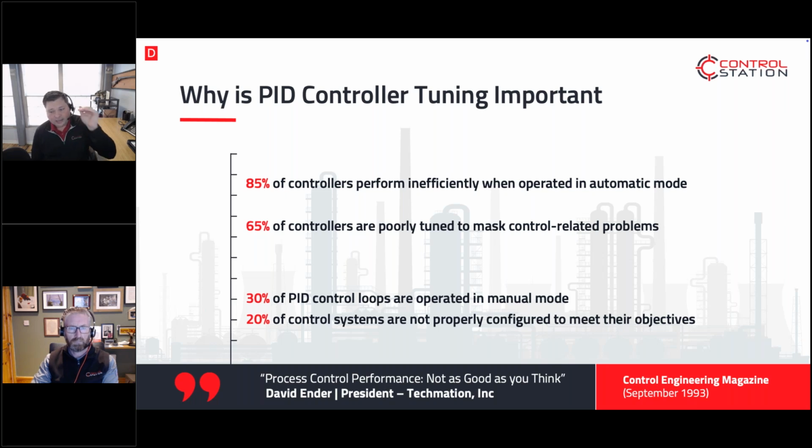We've got clients who have done a lot of continuous improvement and driven their process and hold loops 95% of the time in automatic. Some hit 99%. That is world class, right? But most sites are going to be in that 70 to maybe 80%. It is hard, but it is achievable. You just have to start getting consistent with the effort. It's not just once in a while when there's a problem loop. It does need to be a mindset change within your group.